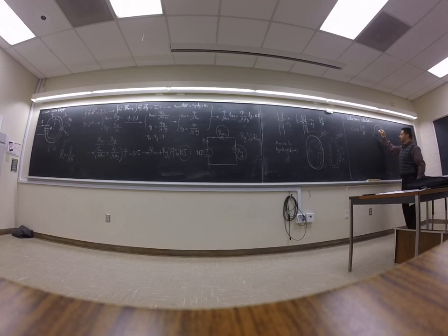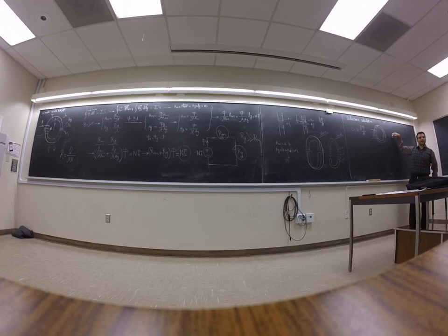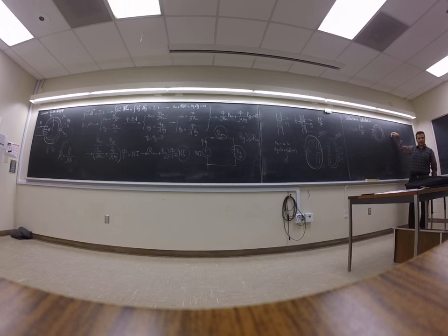For example, somehow you have flux in this circuit. How can you have flux here? If you have another winding here, like a transformer, and connect this one to a source, it's going to generate flux here, right? When it generates flux, this one is going to generate voltage here, right? How much is this voltage? E. And this is an N. You can use Faraday's law to calculate this.